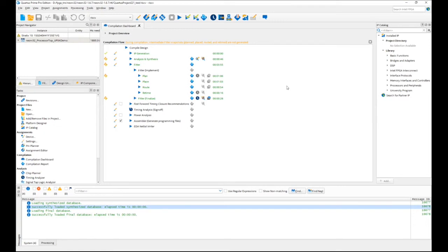Sure. Is a license required for Quartus Lite to use the timing analyzer? I compiled a Max design in Quartus and got an error on timing analysis: license required. That is very interesting. Well, when you install Quartus Lite, you could install the devices that Quartus Lite supports. All of these are supposed to be license free.